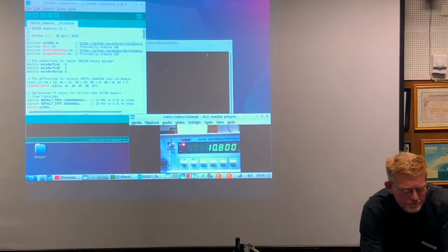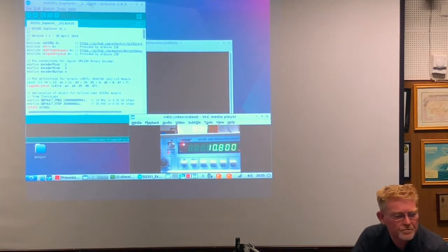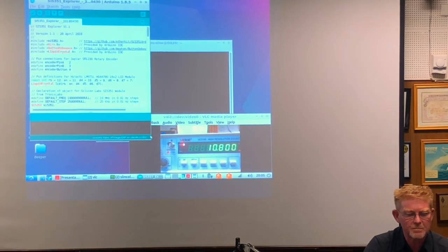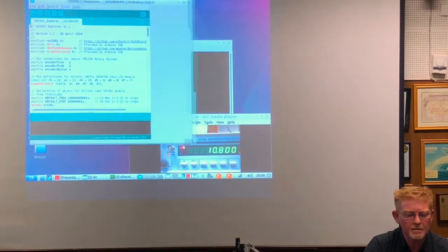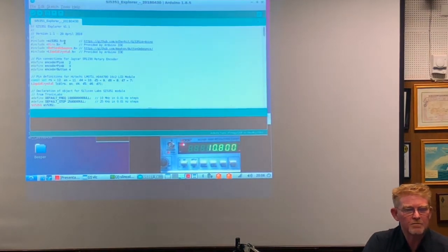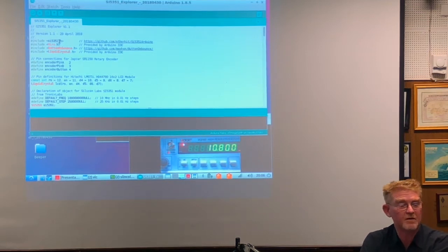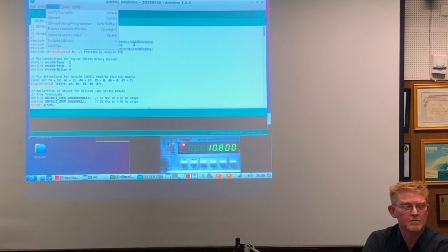the code itself looks a little bit intimidating, but if I work through it, you might find it's not actually as scary as you may think. Now, I mentioned before pre-existing libraries. These lines you can see up here are basically where I pull that code in and tell the Arduino environment, use this code when you make the program. This one here, the SI5351, the signal generator is an SI5351 chip, and the library came from this site on the internet.